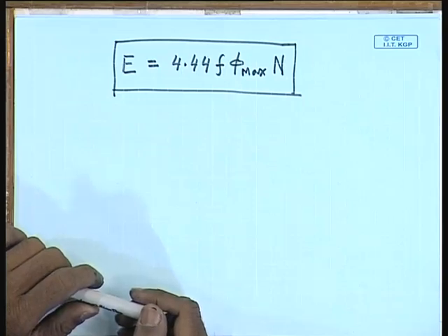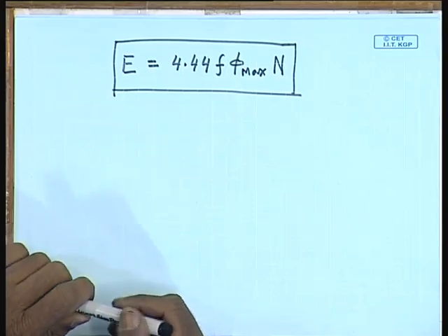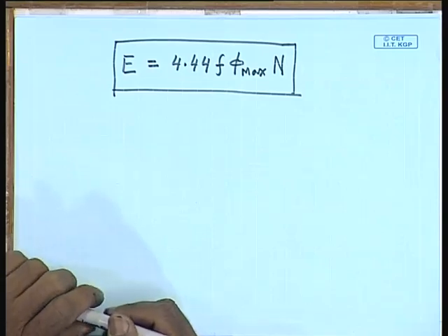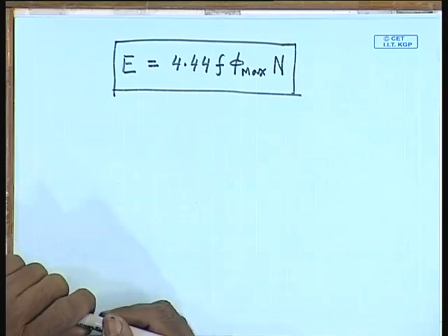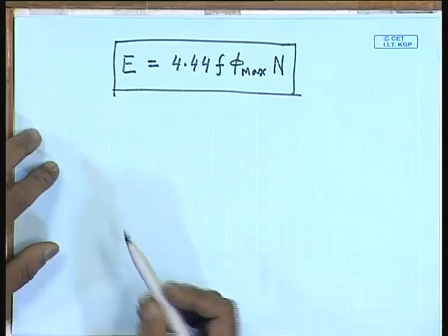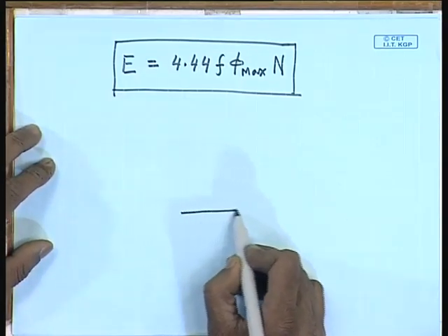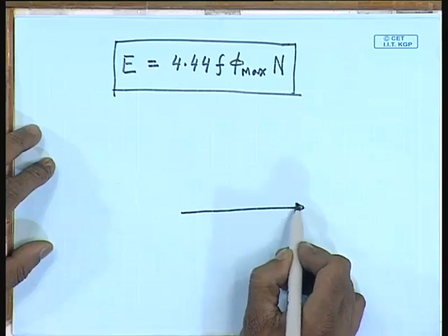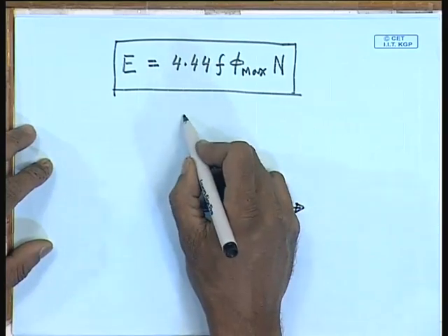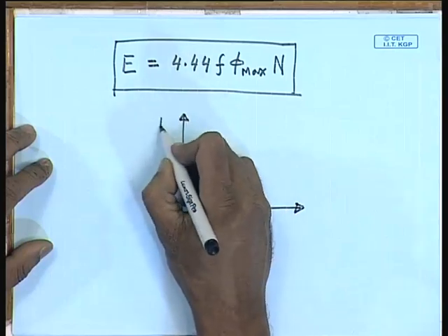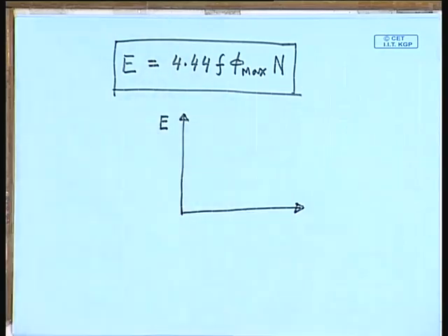which links an alternating flux phi. Generally, alternating quantities in AC circuit analysis are represented by phasors. Therefore, if we draw the phasors and take the flux phasor to be the reference phasor, then the induced voltage E will be leading it by an angle of 90 degrees.